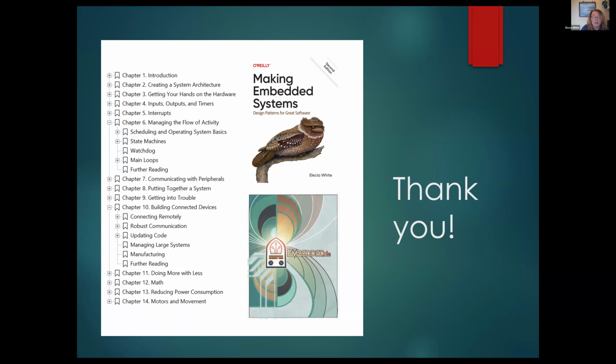If you're doing big displays, Qt has a fantastic emulator, but at some point you have to put it on the hardware. You can't avoid that because there are always discrepancies. And so you have to balance the idea that you will have these discrepancies and they may bite you with the emulator. So make sure you don't just use one or the other.